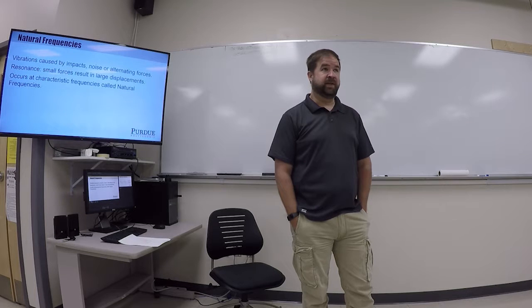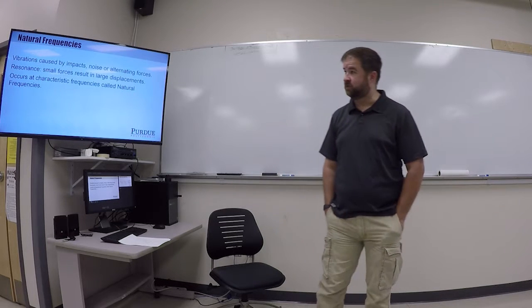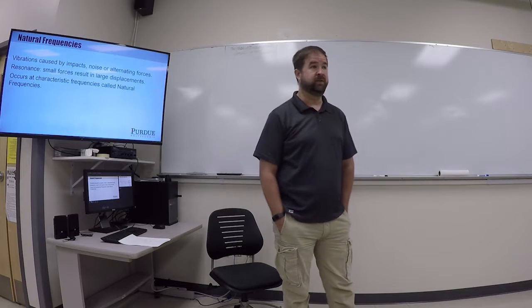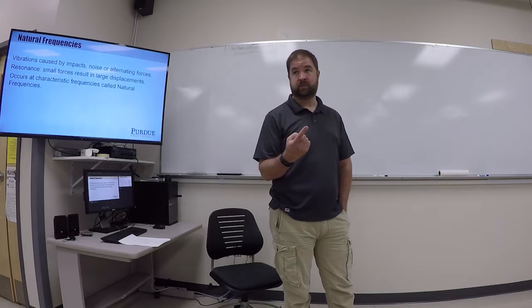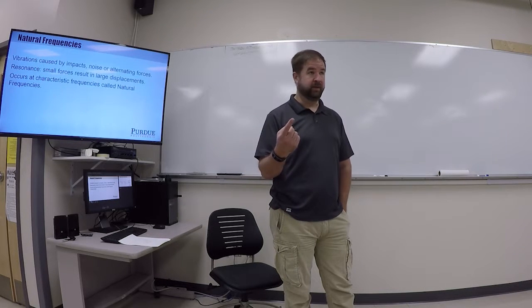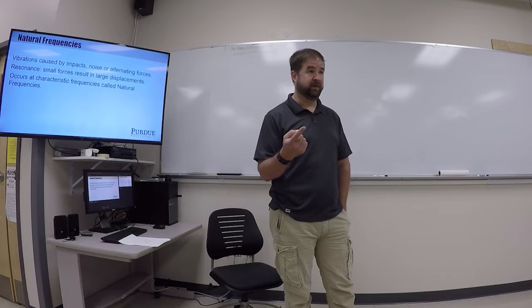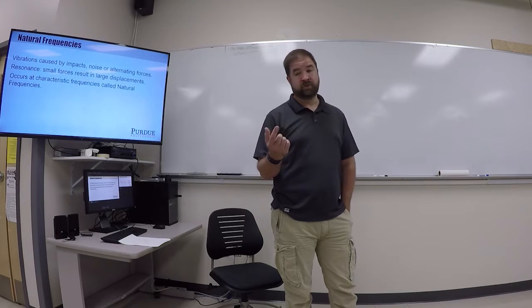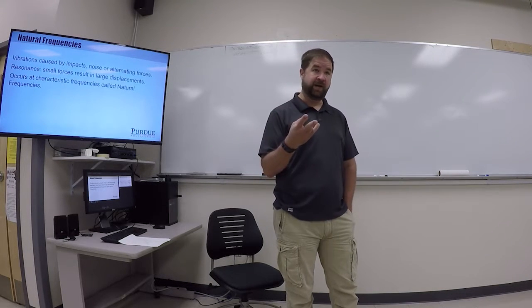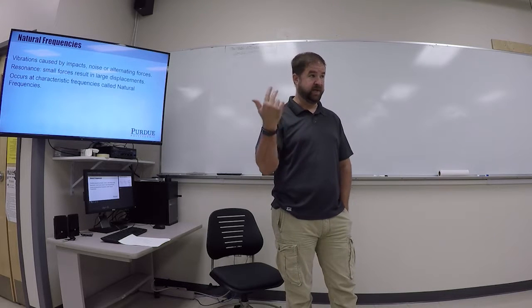There's several different technologies, but what is it that limits the conventional elevator to 1,600 feet? Well, one of it is just the weight of the cable. It gets so long and so big that it becomes impractical to make the cables that long. Interestingly, the other thing that becomes a problem is the natural frequency of the cable that's hanging there.